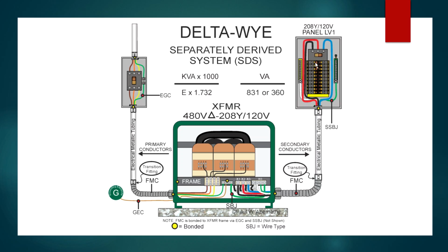When you're dealing with secondary conductors or tap rules, the next size up rule that we used over here does not work over here. You can't use the next size up rule in 240.4(B). So whatever these conductors are, they have to be rated to whatever device they terminate in. And that's a quick tip for the 10-foot tap rule or the 10-foot secondary rule.